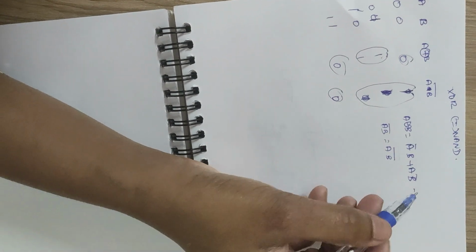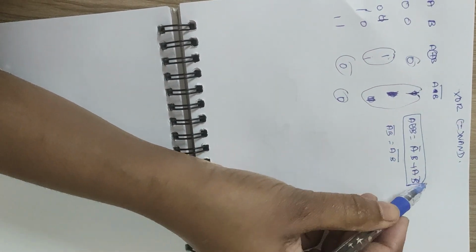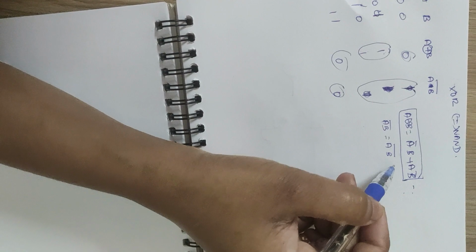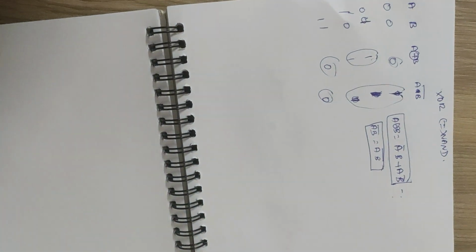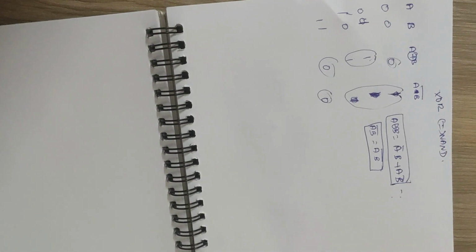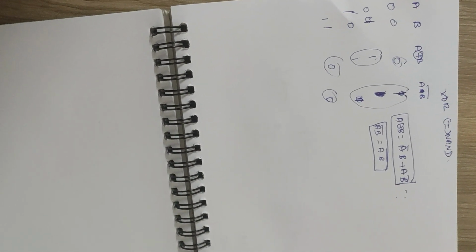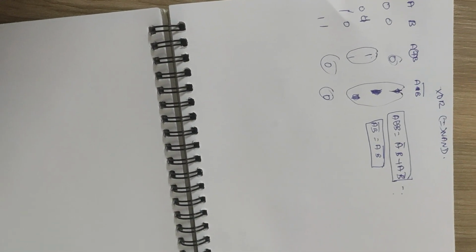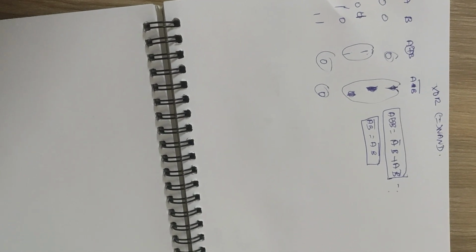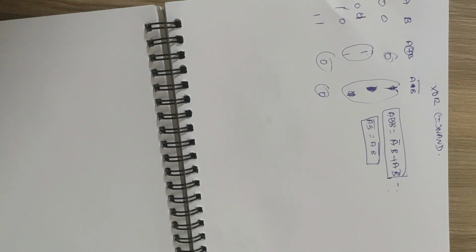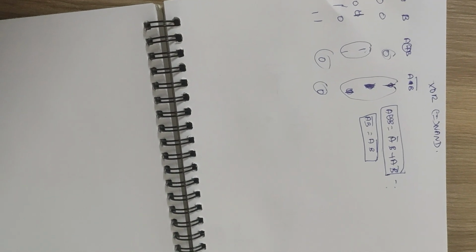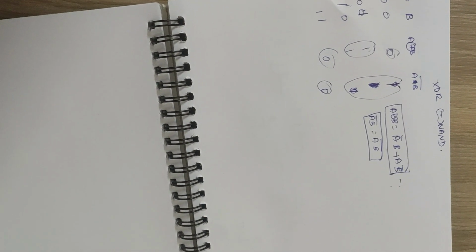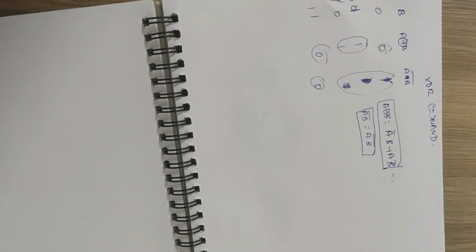This is the expression we need to implement, but we only have the NAND gate, which has two inputs, ANDs them and inverts the result. But I need the functionality A bar B plus A B bar. We have to derive this, like how we do with the truth table.